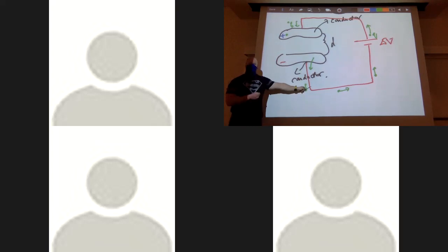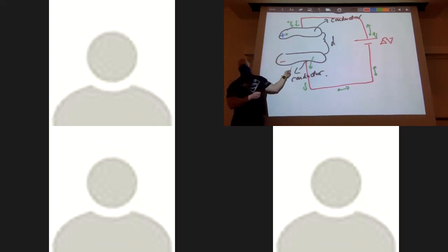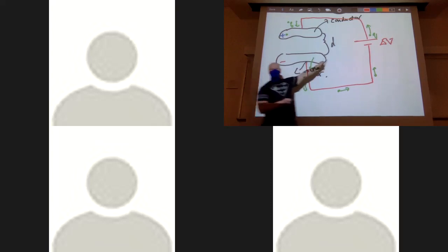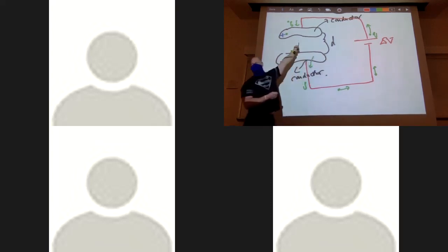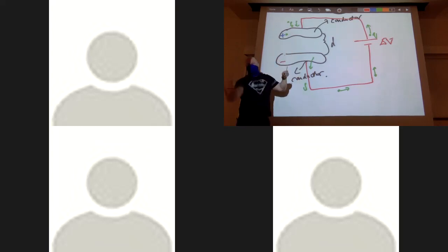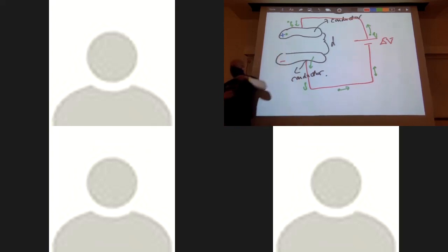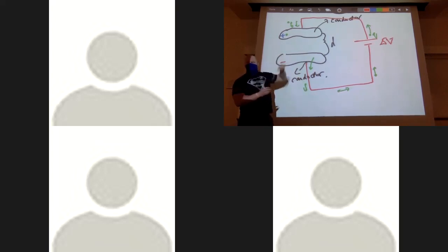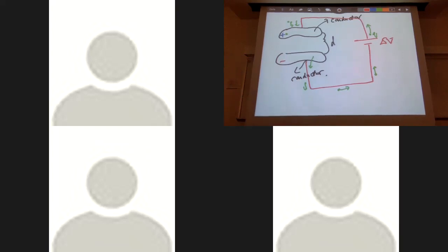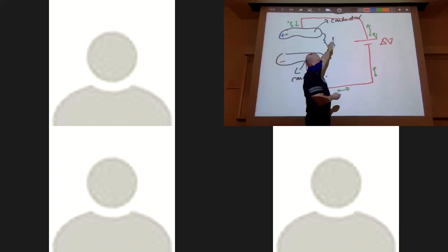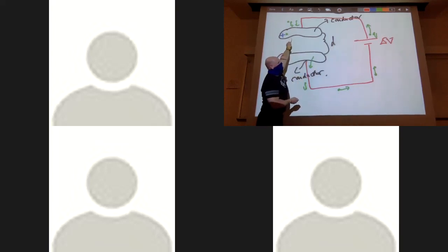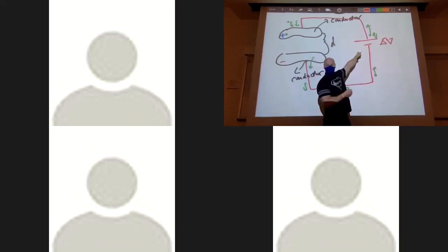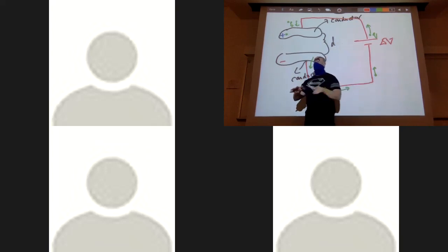Simultaneously, once that charge gets pushed onto this plate, that will cause a Coulomb repulsion on this one, causing this one to move away, which means I'll end up with 2 positive charges here, 2 negative charges here. Then my battery will try to push another charge onto this plate, which means it has to do much more work because there's more charge on here, there's more Coulomb repulsion to get a third charge on there, which then forces 3 negative charges on this one, and then eventually it will stop. Eventually the amount of work required to put a charge onto this plate will be more than the amount of work that your battery can do, at which point charges will no longer be able to be put onto this plate, which means charges will stop moving through the circuit.